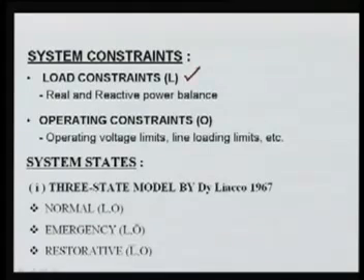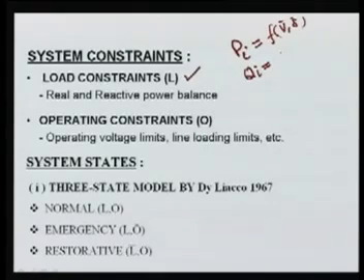This is nothing but your real power as well as the reactive power balance equations. At each node, we can write the P injection at any ith bus as a function of your voltages and the deltas of all the buses. So this is the power balance equation. Similarly, we can write the reactive power injection will be equal to another function, I can say it is G, another equation in terms of voltage and angles. So these are your power balance equations, and it is 2 in number, and it is for all the buses.